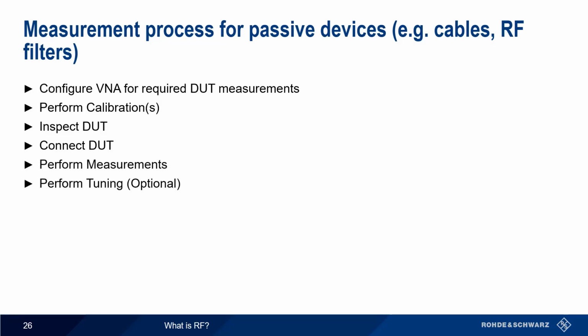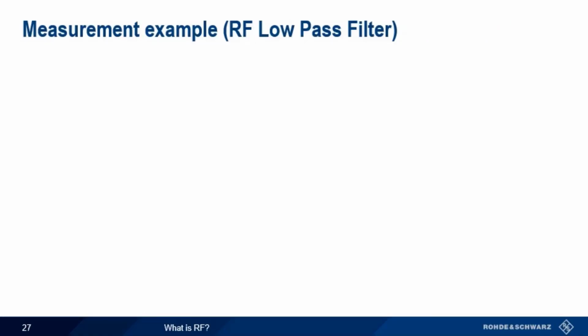Any required tuning, such as aligning RF filters, can be performed. Finally, trace data may be exported for archiving, for reports, or to be used in RF simulation programs. Next, we'll demonstrate this measurement process for a low-pass filter.